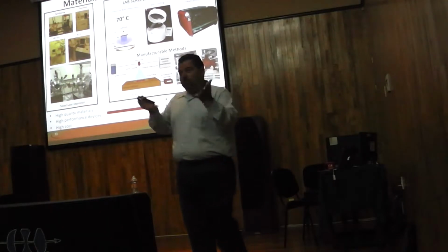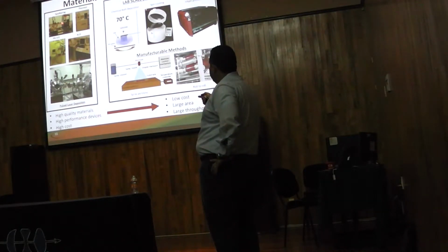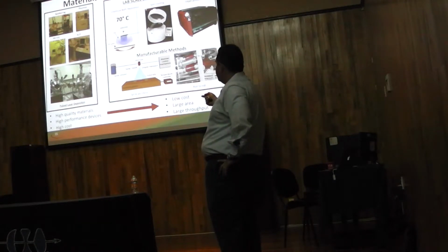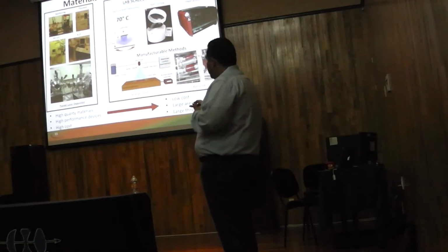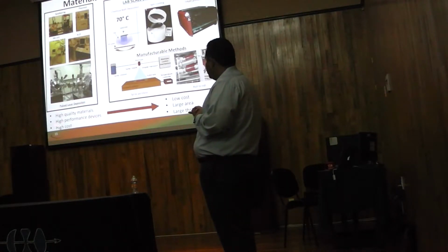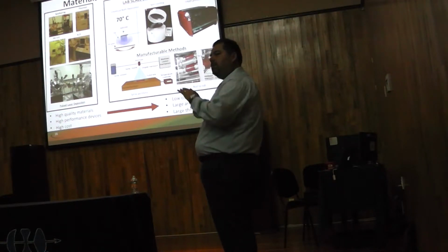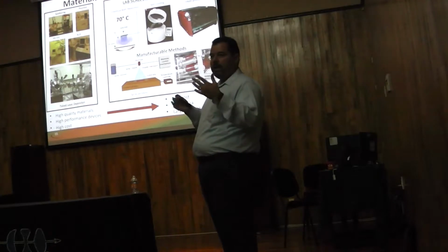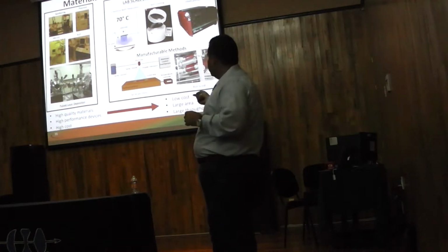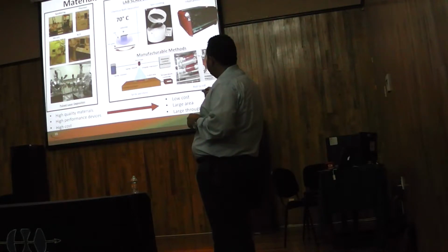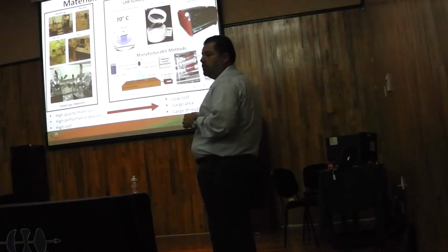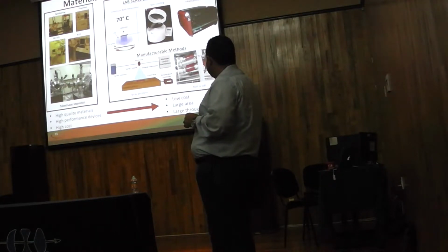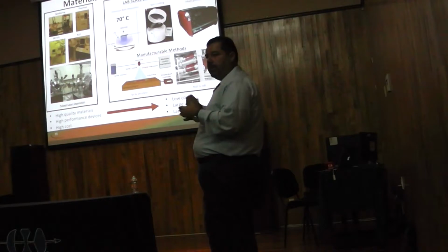The strategy that we follow to do this is, first, we use expensive tools like sputtering, thermal evaporation, PECVD, and in particular in our lab, pulsed laser deposition. That allows us to identify materials that will have high performance, but they are very expensive. But I don't need to worry about contamination, or leftovers from the organics or anything like that. Once we identify the conditions, we transfer these to cheap, inexpensive techniques: chemical bath deposition, spin coating, we have the Ninja printer as well, and roll to roll. These techniques are low cost, large area, and large throughput, very fast.